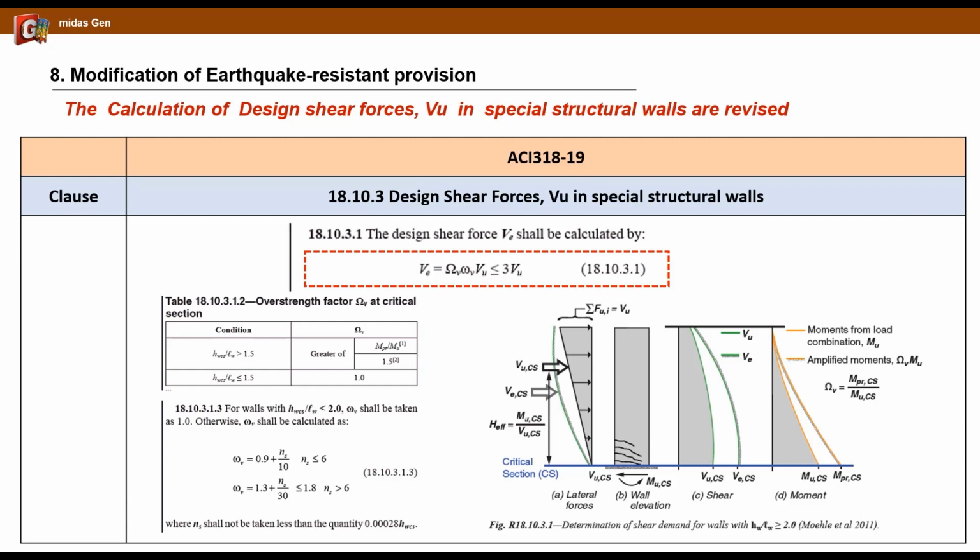Although the value of 1.5 in 18.10.3.1.2 is greater than the minimum value obtained for the governing load combination with a phi factor of 0.9 and a tensile stress of at least 1.25 fy in the longitudinal reinforcement, a value greater than 1.5 may be appropriate if provided longitudinal reinforcement exceeds that required.